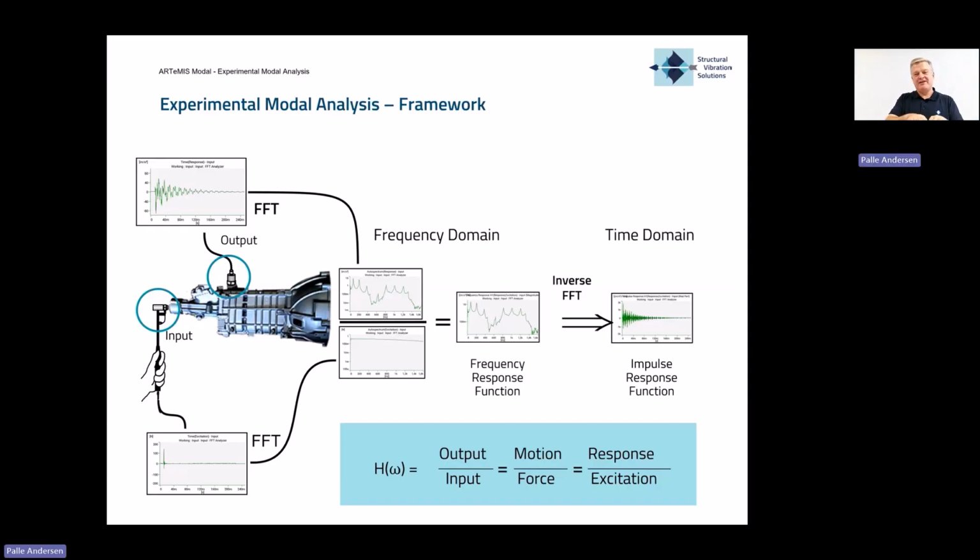And this is close to what we would call a white noise excitation. If it's completely flat, it's completely white noise. But normally you'll see that it dies out a little bit in the higher frequencies, but still very flat, exciting all the different frequencies in this range that we're looking at. These two here we can in different ways divide with one another.